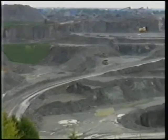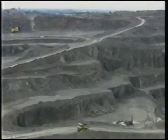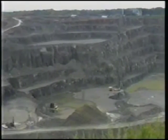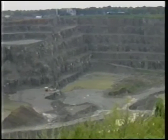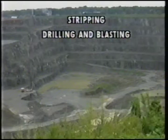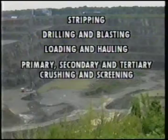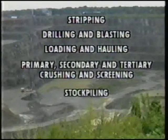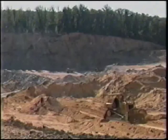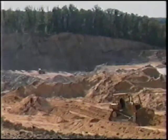The production of aggregate materials is comprised of 6 basic processes which are performed using various methods and equipment depending upon the many variations in which aggregate deposits are found. The basic processes are stripping, drilling and blasting, loading and hauling, primary, secondary, and tertiary crushing and screening, stockpiling, and finally, load out. The first task in the production of aggregate is uncovering the deposit to be mined.